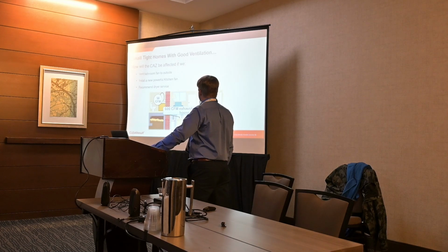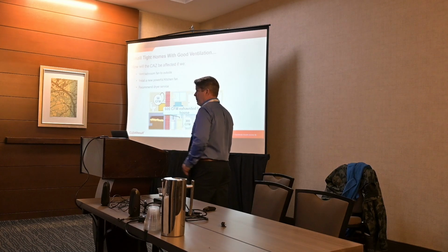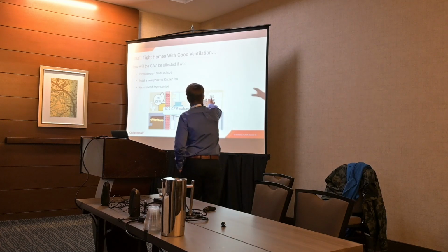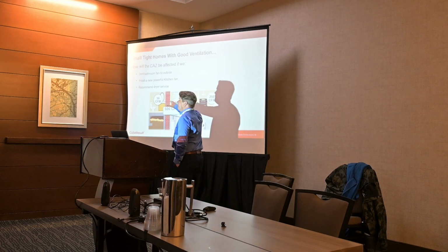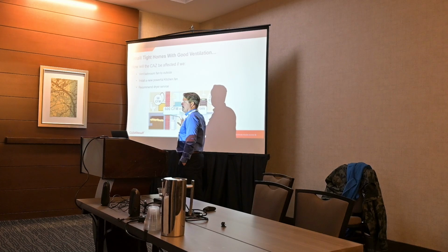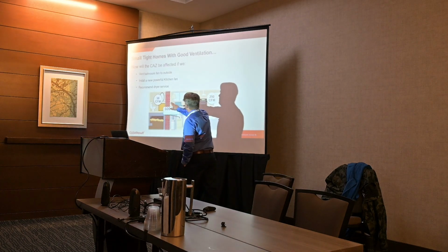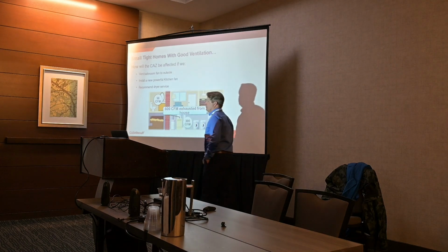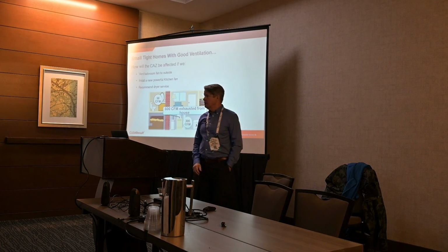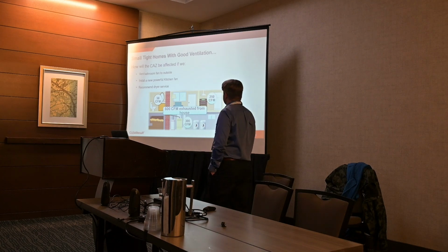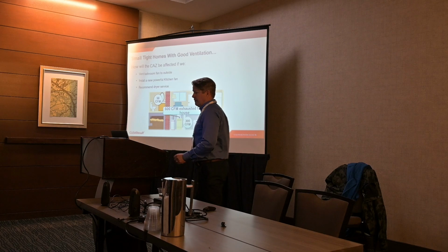So combustion safety testing is very important. What do you mean by well ventilated? Good spot ventilation, right? I'm not talking about attic ventilation. I'm talking about kitchen fan, bathroom fan, and a dryer. Exhaust appliances. Yes. Anything that takes air from inside the house and expels it to the outside will reduce the pressure in the house significantly if it's tight.